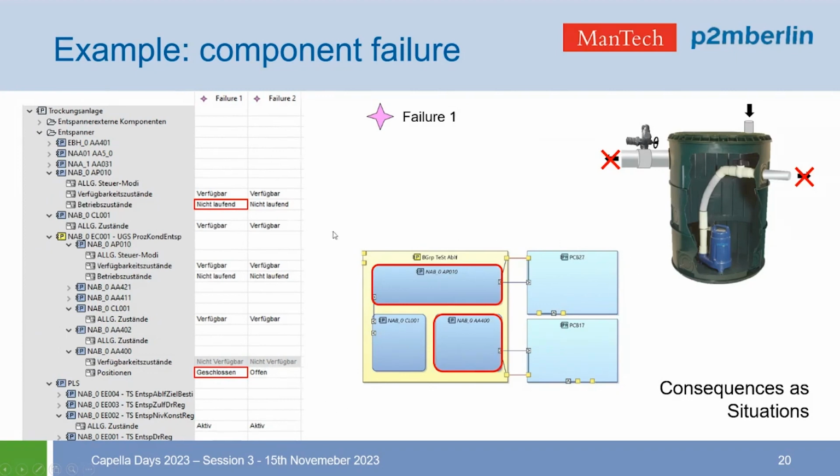When we look at the structure diagram, we can see that the components that are, let's say, not allowing any flow in this configuration are the pump and the valve, which are the only two ways out for the fluid from the tank, which means that this situation is not desirable. It will probably lead to an overflow of the tank.